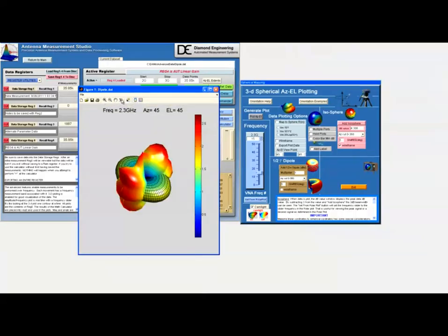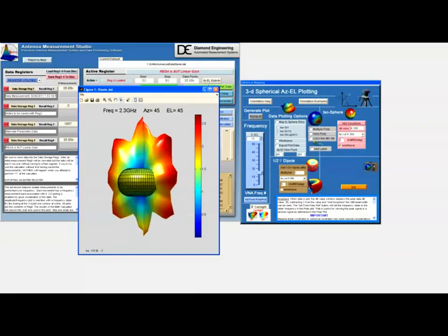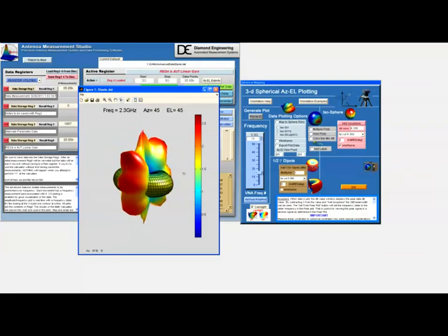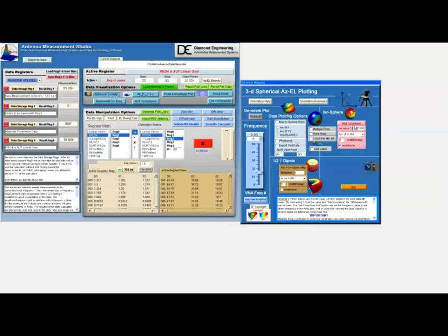Along with this option, we can also add isospheres. The maximum gain for the plot appears in the dB value window. In this case, it's 4.3 dB. Now we're going to add an isosphere with 2.3 dB gain. So I'm adding an isosphere and a half-wave dipole.